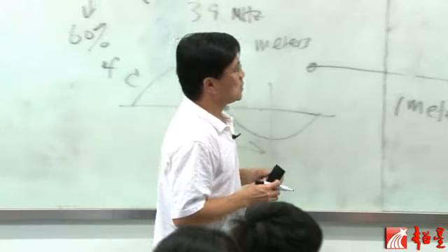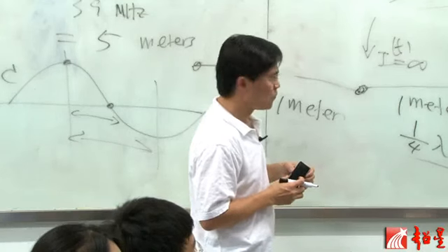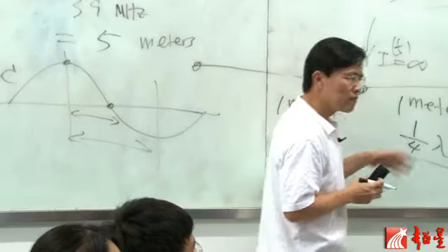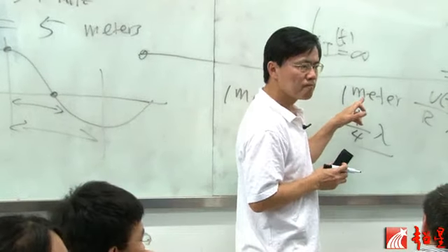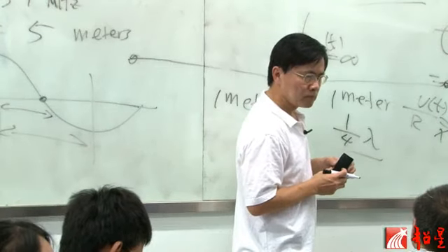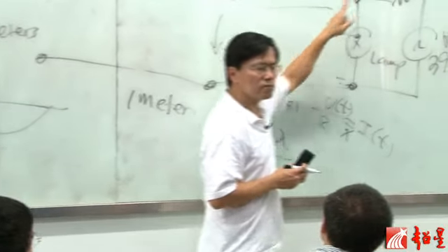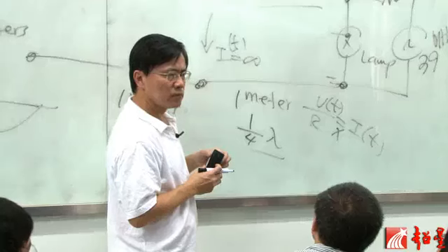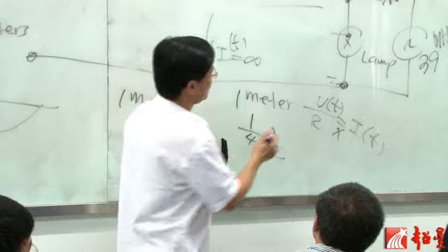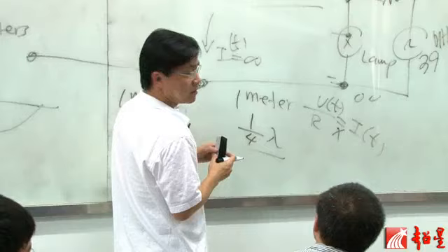Yes. Why don't you discuss the point on the bottom? If the voltage in the upper point is 0, but the voltage on the other point is not 0, then that can still be turned on. No, we're assuming this is the 0 volts reference.